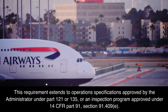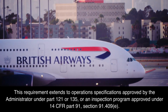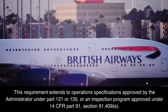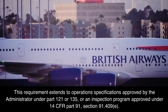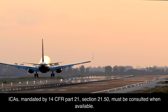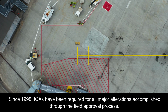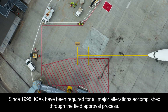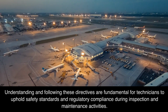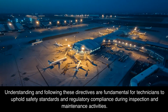This requirement extends to operation specifications approved by the administrator under Part 121 or 135, or an inspection program approved under 14 CFR Part 91, Section 91.409(e). ICAs, mandated by 14 CFR Part 21, Section 21.50, must be consulted when available. Since 1998, ICAs have been required for all major alterations accomplished through the field approval process. Understanding and following these directives are fundamental for technicians to uphold safety standards and regulatory compliance during inspection and maintenance activities.